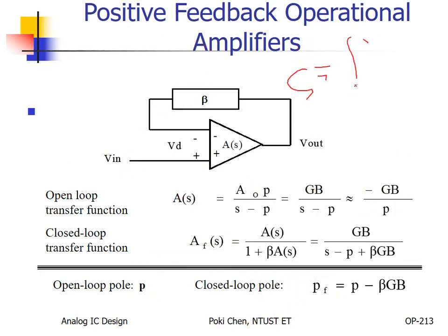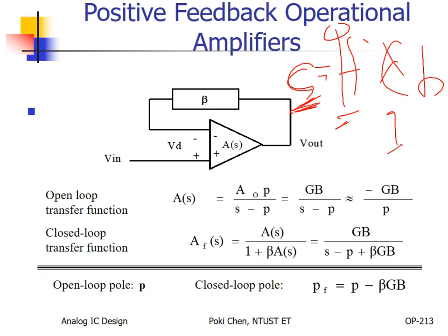C equals f lambda, right? That is the light speed. Never mind, you use laser or RF wave, I don't care. But for frequency, LiDAR means light. The frequency is much higher than radio frequency, right? So it means what? The same light speed in the air, but LiDAR using laser gets much higher frequency than RF wave, so the lambda is much smaller. And lambda is strongly correlated to your distance resolution.